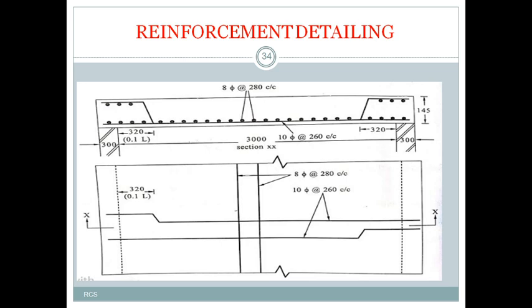of the slab, and the minimum required depth of the slab should be compared with the provided depth. If the provided depth is more than the calculated depth, that is the required minimum depth, then we adopt it as the assumed depth for further proceedings. Then we have to calculate the area of steel provided in the slab by using the Codal formula. Then we have to check with the Codal requirements. Then we have to go for checking of deflection.